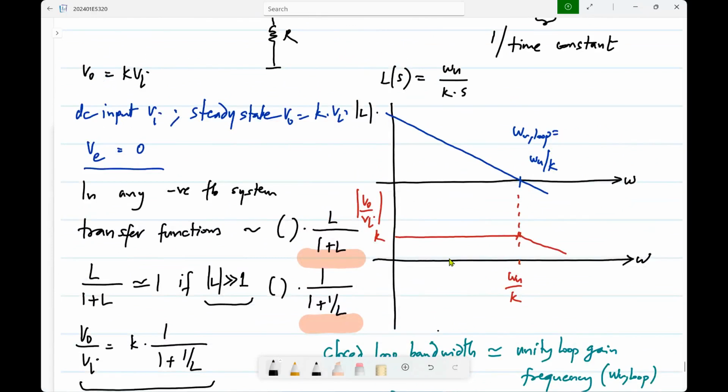And you may have seen this in the lab also. If you have made these amplifiers, you will see some ringing, and then you put your finger on some node and it goes away. And it could be that the parasitic capacitance of your finger is actually slowing the circuit down, and that's why it goes away. Okay. In the worst case, you can always make the system well behaved by making it very slow. Of course, that's not always what you want to do.